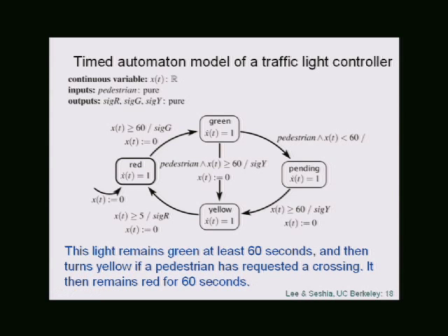Okay. Ideally, what you should be careful about when implementing that is that if your system really depends on the exact values of delays, then you have to be aware that your timers may not be perfect, and they may not measure time intervals perfectly. So rather than having x equal to 60, as we had discussed earlier, you want to have 60 minus epsilon, 60 plus epsilon, something like that. So give it a little bit of tolerance to deal with any skews that you might get. Okay.